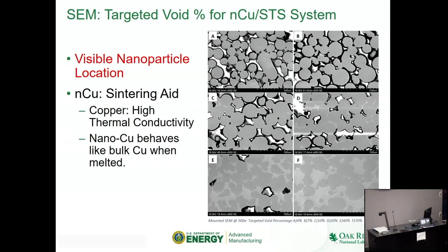Sintering is basically where you have these larger metal particles forming necks in the presence of high temperature. They form these necks where they come together, and so your grain boundary is shifting and changing.